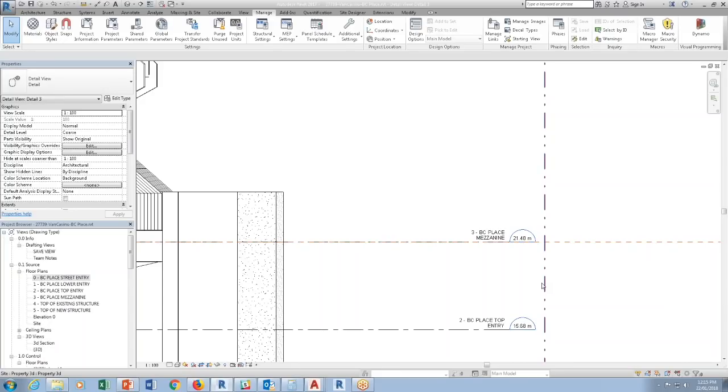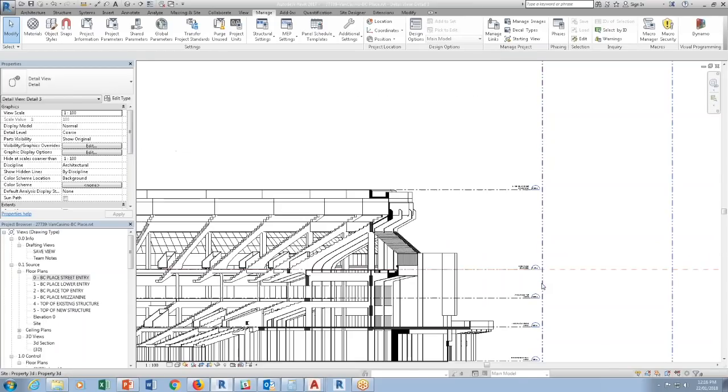The other option you could do is create a link. You basically create the 3D property line and put it outside, and then you link them in. Once you link them in and create that setting, you can still do keynoting. But I have to experiment more because I'm not really sure that this will help. Keynoting is very, very sensitive. It just wants to know if there's an object. If there's an object, it will just pick it up.